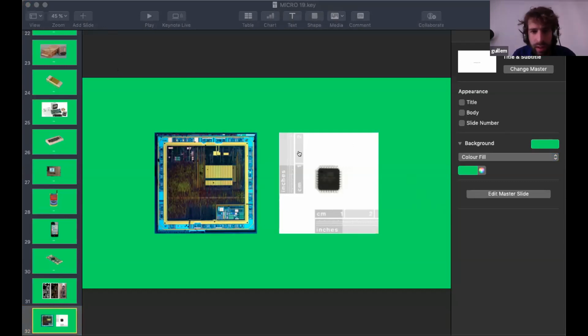So if you look inside this board here, you might think that black box is also a microcontroller or a microprocessor, and in fact it is not. That's a board designed to put on top of a Raspberry Pi, and this is simply an analog to digital converter with an amplifier. So it's a board that's designed to transform digital audio into analog audio and to drive a speaker. Sorry, Guillem, I don't think we see what you're showing us.